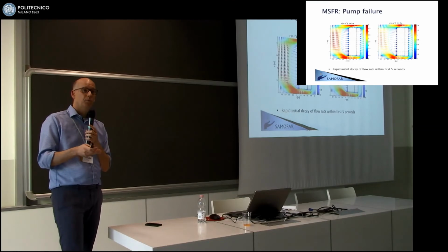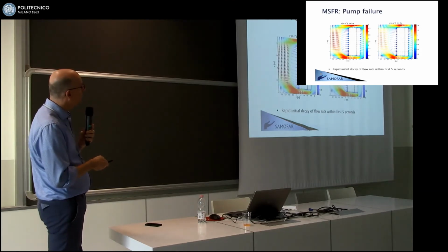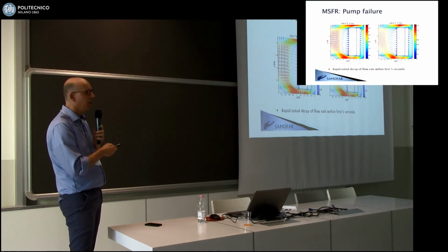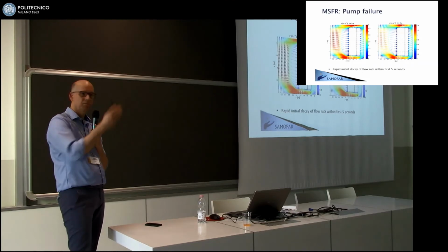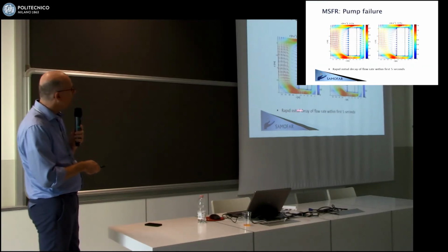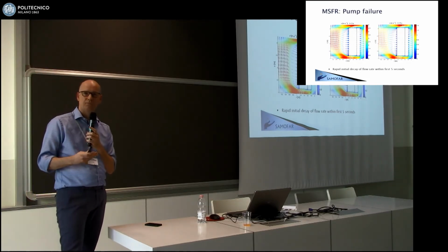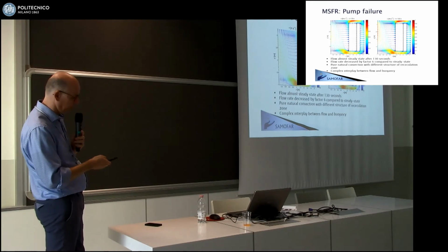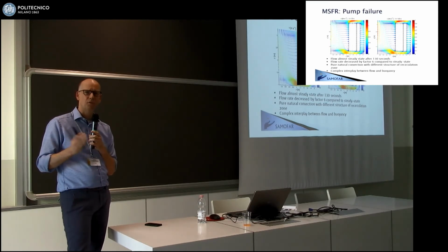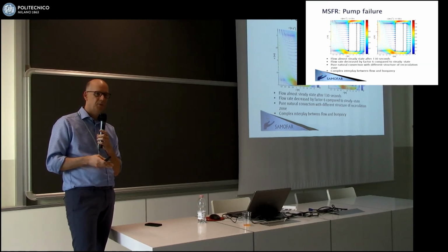Now again, here too, the real strength of multiphysics is in accident scenarios. And one of those scenarios is a loss of flow. And here, I guess, well, I can't really remember exactly, but it was ramped down in a very short time to either 0 or a very small value. And you see that in a very rapid initial transient, your flow tends to decrease by a very large amount. And if you wait long enough, then you get into a natural circulation mode, where the total flow is about 1/5 or 1/6 of the initial one. But still, this is a rather benign transient.